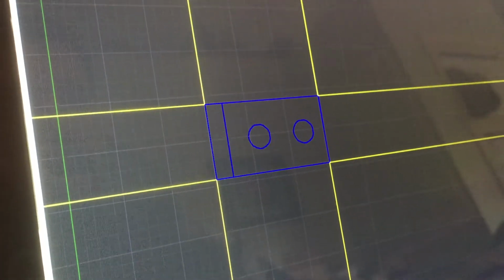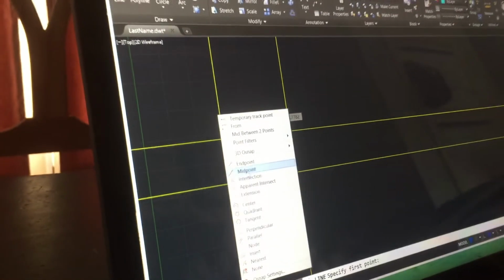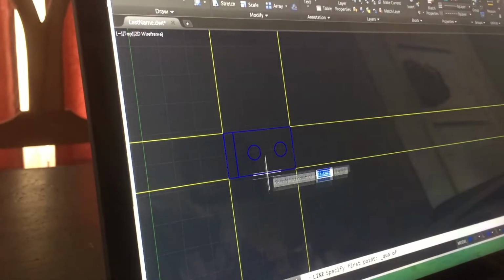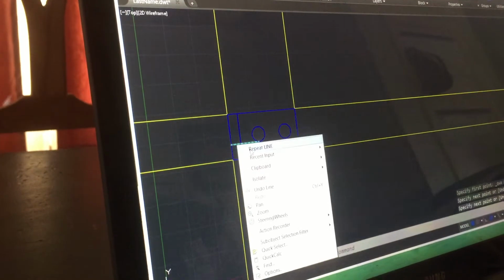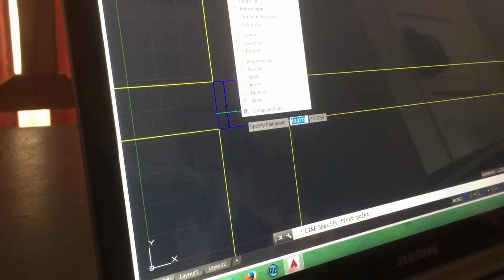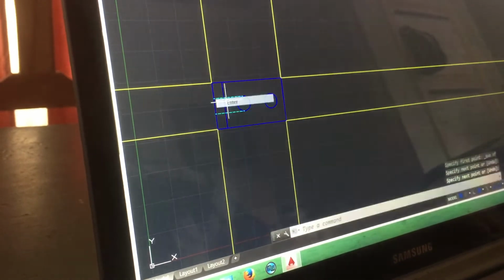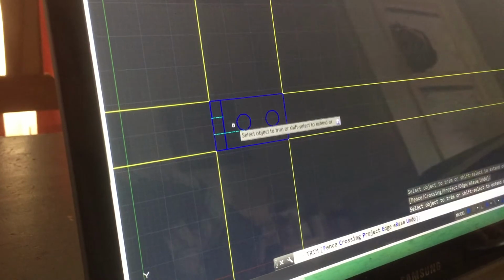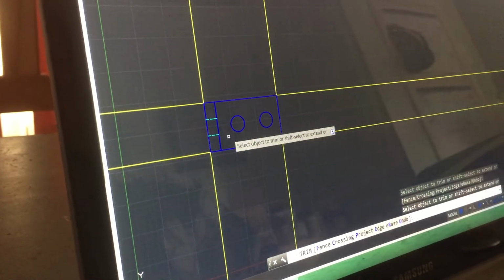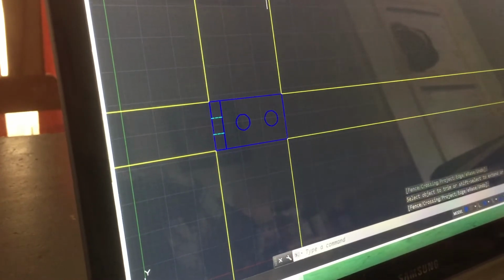So I'll get rid of that center line. I'll come up, I'll change it to hidden. I'll select line and quadrant. I'll repeat the line. Select quadrant, and then I will trim those 2 lines. Now that gives me my front view of that object.